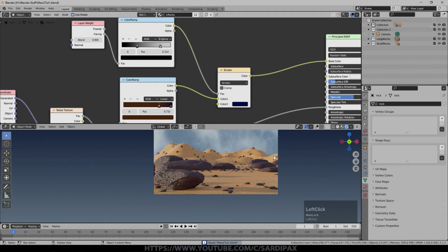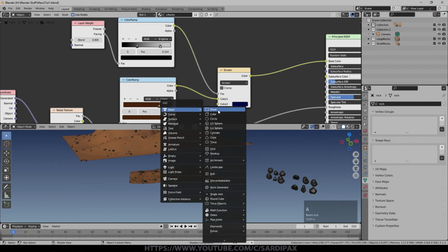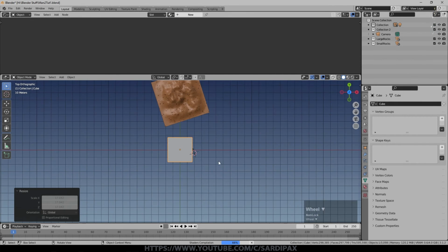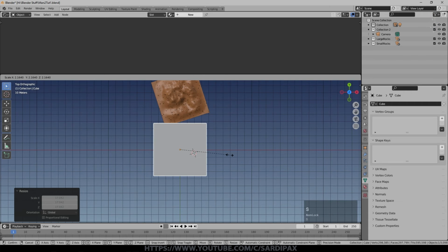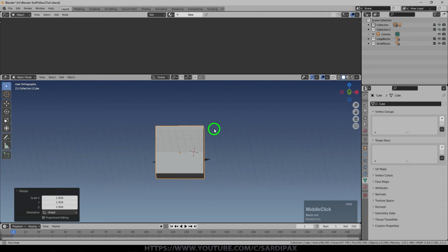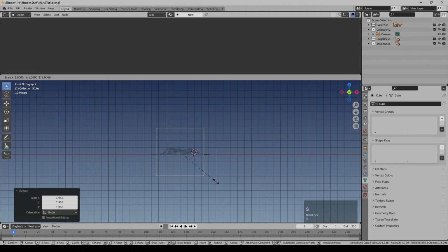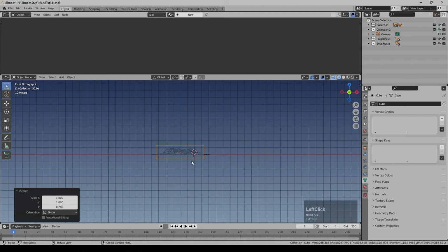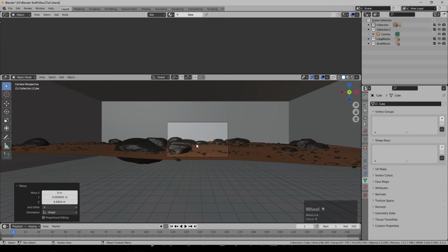So having done the rocks, we're now ready to add the mist. So I'm going to add a mesh, which is a cube, and we'll just drop that over our landscape and size it up. I think I ended up enclosing even the remote landscape. It's not that important, as long as it encloses all of the landscape that you have. It doesn't, however, need to be all that high. You don't really want to see corners and things like that. The camera's now inside that box, mist or dust, whatever you want to call it.